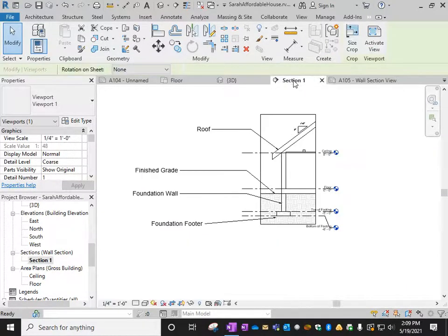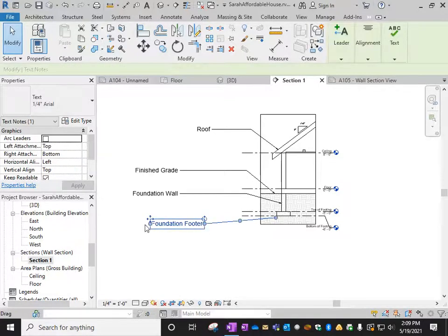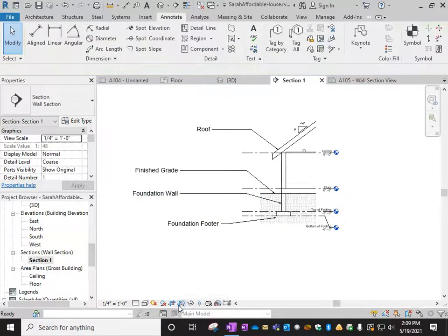What I'm going to do is go and clean things up with the new scale in the section view. All right, and so I will just clean everything up, make sure that it all makes sense, move things around so that they're not overlapping and so that they're lined up nicely. Once you're all done with that, turn on hide crop region, the actual boundary, but make sure that it is cropped. And let's assume that everything here is in perfect condition, which it's not, but you would make it look a little cleaner here.